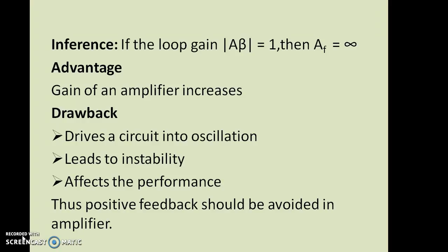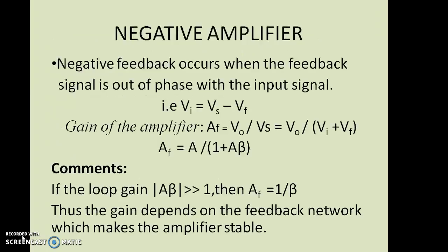There are some drawbacks in positive feedback. One, it drives the circuit into oscillation. Second, it leads to instability. And finally, it affects the performance of the amplifier. Thus, positive feedback should be avoided in amplifiers. It can be used in oscillators.